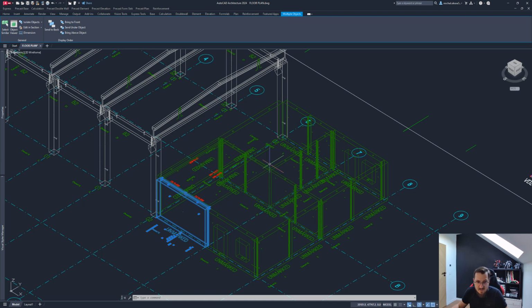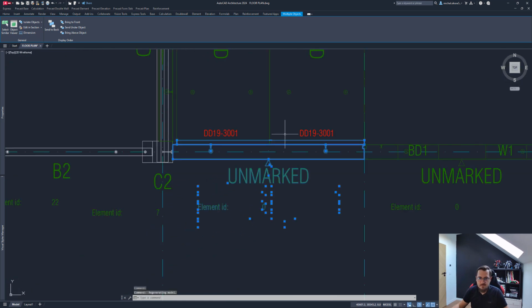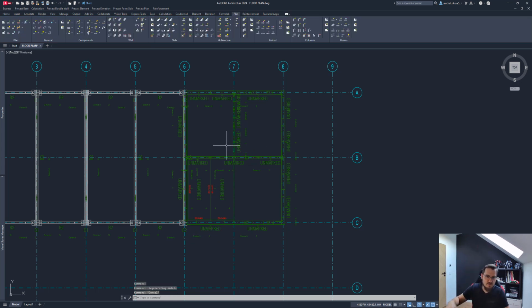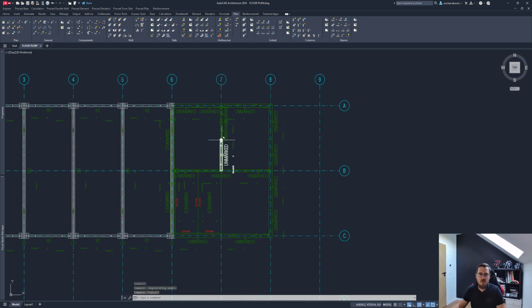Now let me go ahead and save everything to the database. And once we do that, we'll look at the 3D model that's been updated, and after that, we'll just go ahead and start working our way into the reinforcement drawings, at least a bit. All right, so to save the elements, we go to the Wall tab, we select the Save to Database option, and let's select all slabs. Automatically, let's first save the sandwich panels, right? Let's save those. So I'm now saving those with an element mark SW1 as the first one. I'm waiting for that to go through, and as you can see, it went through.